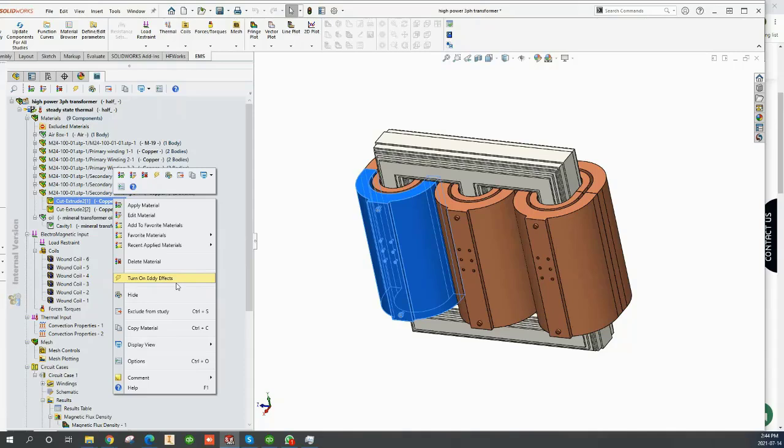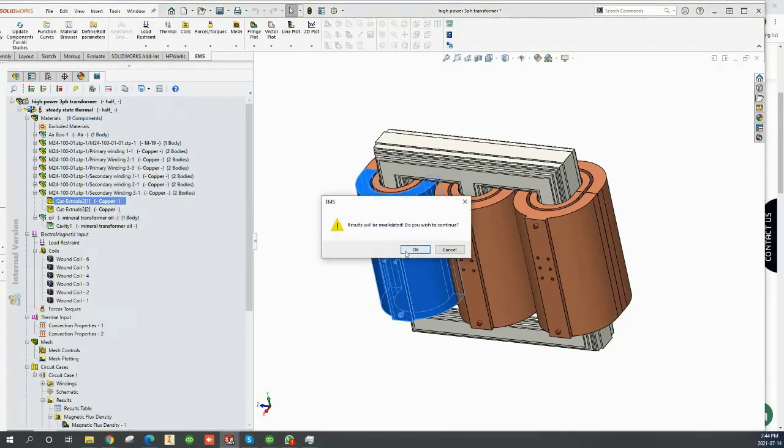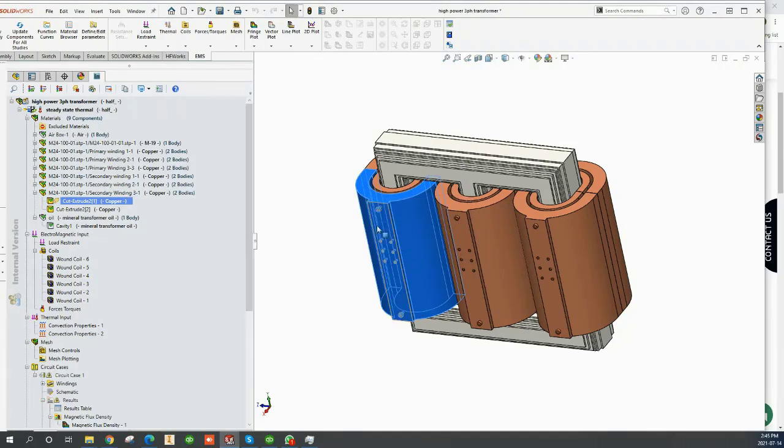In the T-omega technique, you have what is called the T vector, and the T vector is going to give you a lot more unknowns or degrees of freedom. Of course, if you need it, you turn it on. That means in this part, it supports eddy currents. You choose, depending on your application. If eddy current is important to you, you turn it on. But we made it very easy: if I don't want eddy current, I come back here and turn it off.